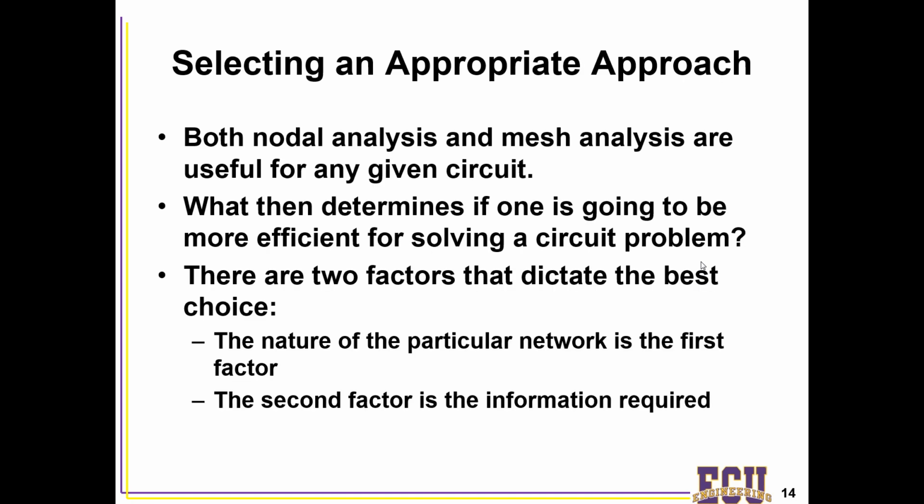So you might ask yourself, how do I choose whether I'm going to use nodal analysis or mesh analysis? Well, in some cases, one is going to be more efficient than the other. You might have a circuit that has a whole lot of nodes but doesn't have as many meshes. In that case, realize that for every non-reference node, you're going to have an equation, and for every mesh, you're going to have an equation.